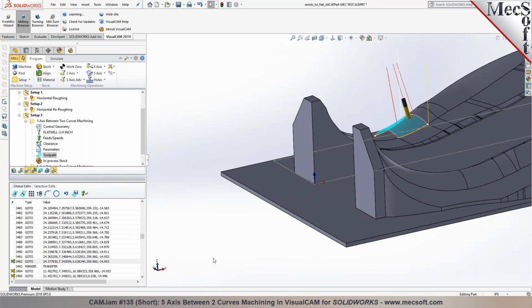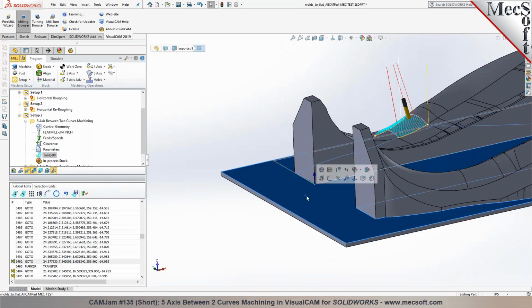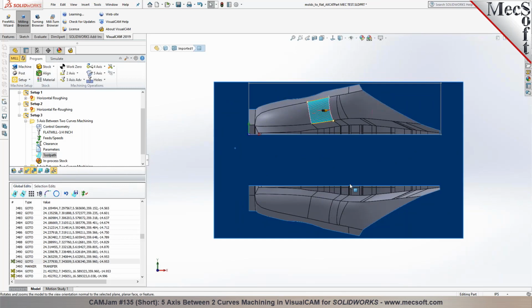Here, go to the top view, Uday, and let's just look at the origin really quick. I can show you. Okay, so see the red arrow? Imagine I'm looking down the top of the machine. That's where C0 is, and then it goes counterclockwise positive 360. That's correct. That's how we define the machine tool right now.